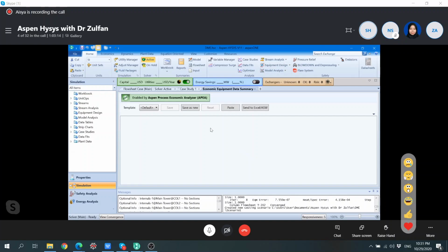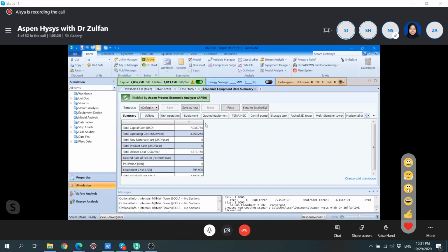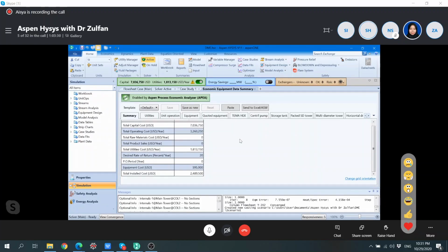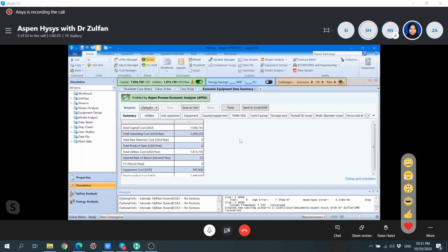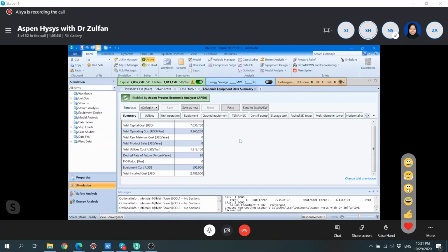The cost estimation from this one click button uses typical or default numbers to design, because to be able to calculate the capex, as you understand from your PDP class or plant design class, you will need to size it, and how they size it is using default values. These default values may be right in some cases, but wrong in other cases.